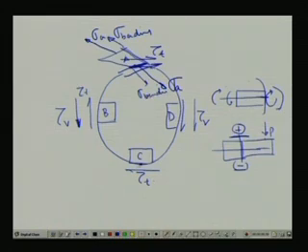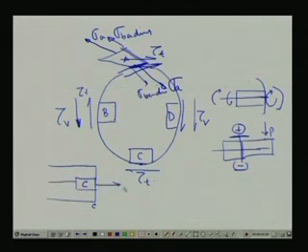Similarly, onto this face, which as a matter of fact we cannot see because this is the cut section, we have to see the surface. That means if it is C here, rotate it, so C comes over here. So, what are you getting? This is sigma axial, and you are having a sigma bending in a compressive manner. And the shear stress goes as it is. This is a shear stress because V was not there.